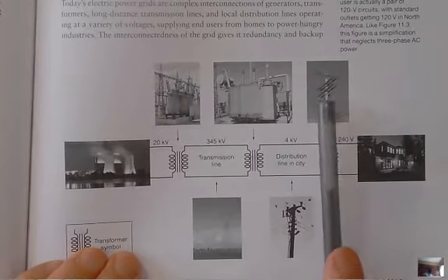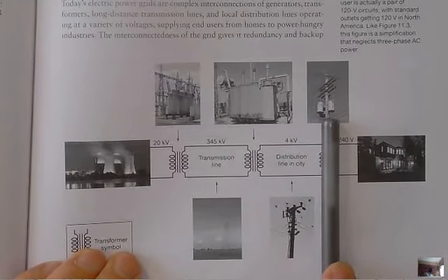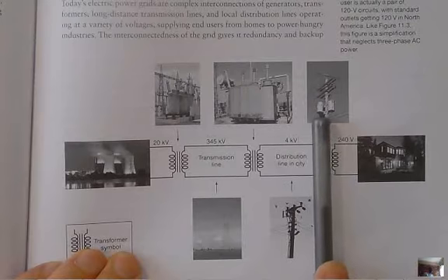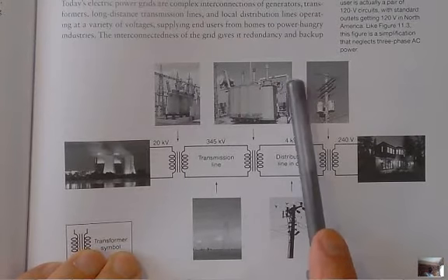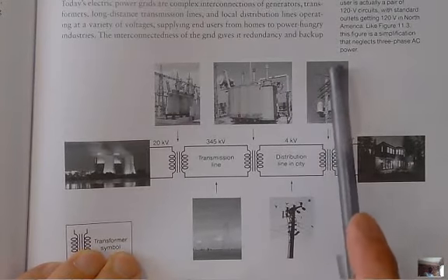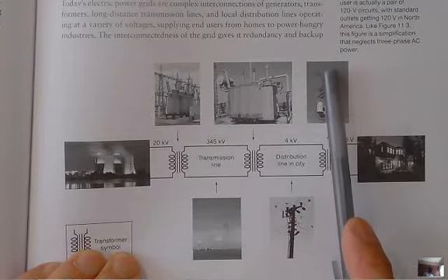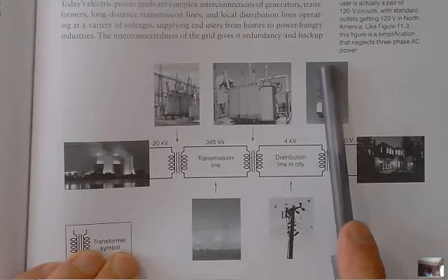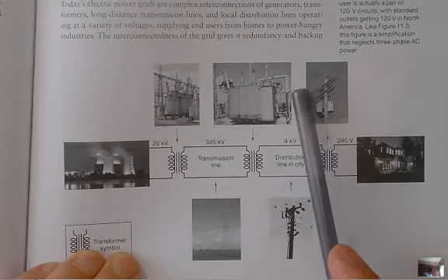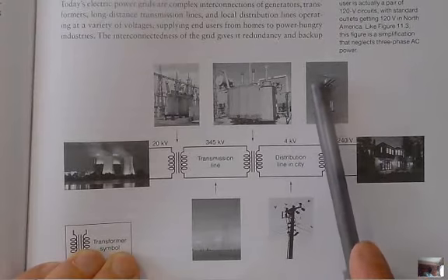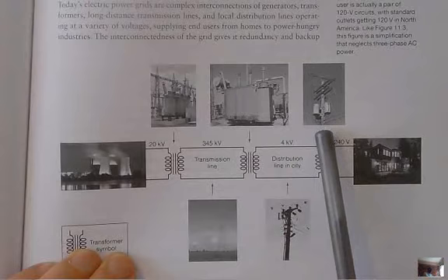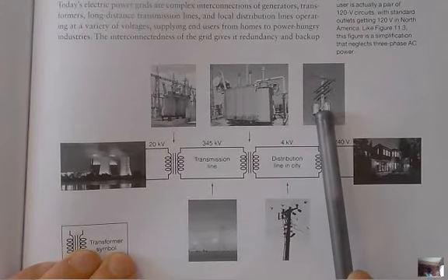The power lines along here, guys, are the lowest ones. The reason they're the lowest is that the higher ones are the most susceptible to being hit by lightning, and they don't want them to get hit. So up at the tippy top is just a ground wire. It's designed so that if lightning does hit the pole, it gets carried directly back down to the ground. So if you look at the top of a telephone pole, the wire up at the top is just the grounded wire. Then there's usually communication, so cable and all that kind of stuff, and lower than that is usually where the electric is.